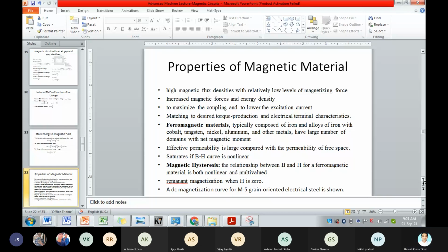Our magnetic material depends on what type of application we are doing, such as when we want a permanent magnet. The properties for permanent materials will be different, and we are selecting the material for the permanent wound coil magnets, and we also want the materials for high frequency applications, such as ferrite core we will use, such as inductors used in electronic circuits such as a charger, you can see.